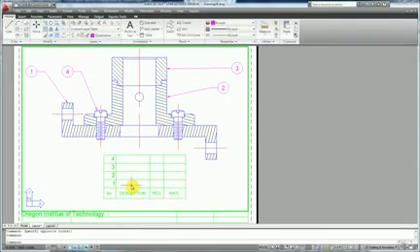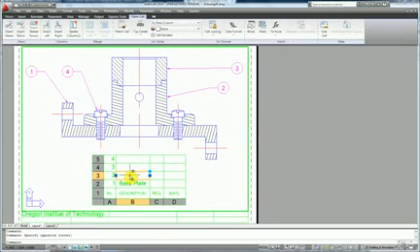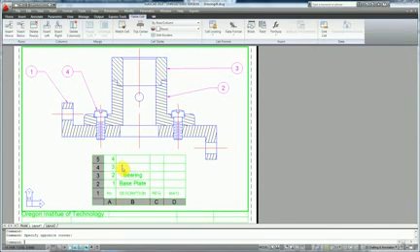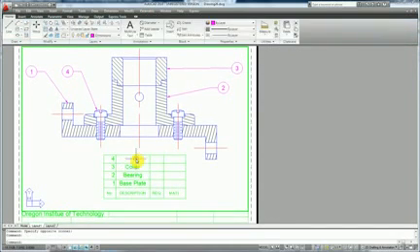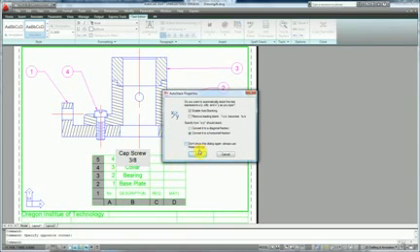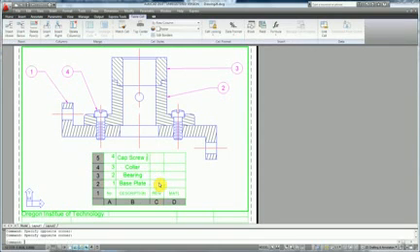Description will be the base plate. 2 is going to be the bearing. 3 is going to be the collar. And 4 will be the cap screw with a reference size of 3/8. AutoCAD will prompt you asking if you want to clean up that fraction to a tighter fraction, so I'll press OK. Notice how it changes size. And then for required parts, all these are 1 except for 2 cap screws.